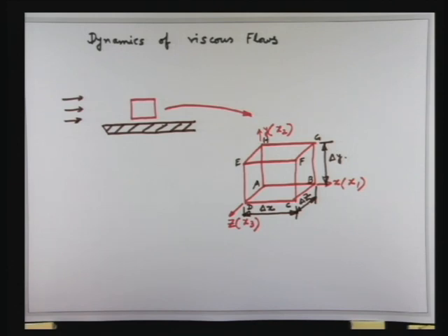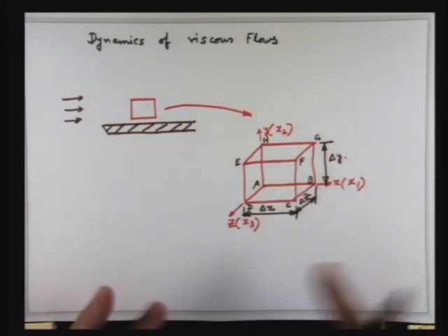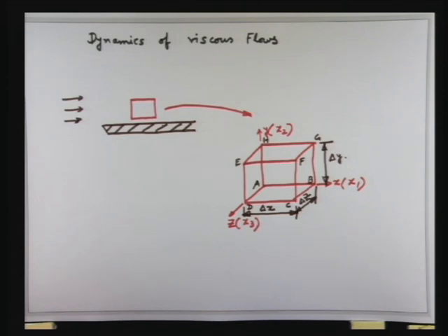fluid element. The component of the stress which is related to deformation, we have to understand that the hydrostatic component is not related to deformation. So the component that is related to deformation is called the deviatoric component. So we have both hydrostatic and deviatoric component, and the total stress is a sum of the hydrostatic and deviatoric component. So in this figure we will not show pressure separately. Pressure is already included within the stress in the form of hydrostatic component.